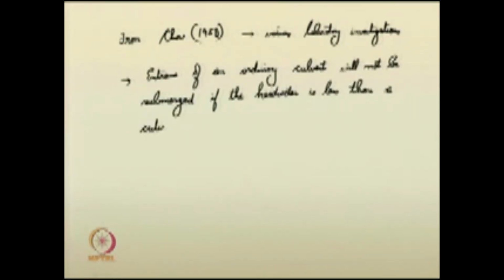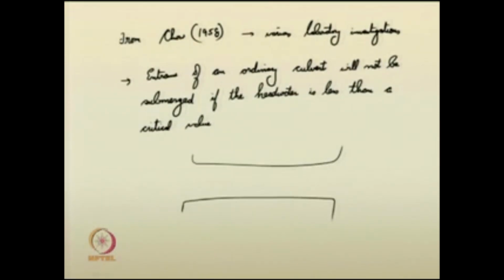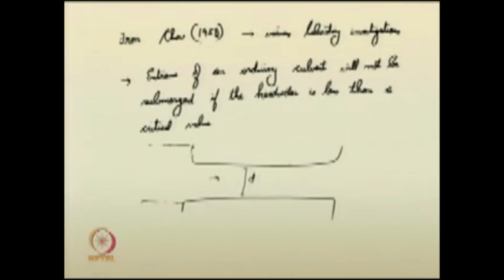What we want to suggest is that, again on the vertical section, even if the headwater is a little above the top of the culvert barrel, this is the barrel depth, this rise does not guarantee that the flow inside the barrel will be full.